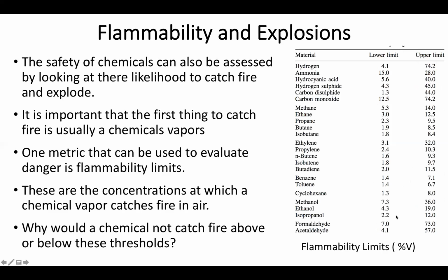So a lot of features on trying to limit flammability are going to be making sure that any fuels are in a rather small container. That way, there isn't enough headspace to allow significant concentrations of oxygen present, or to make use of good ventilation to make sure that any fuel that's evaporated into the atmosphere is quickly dispersed.